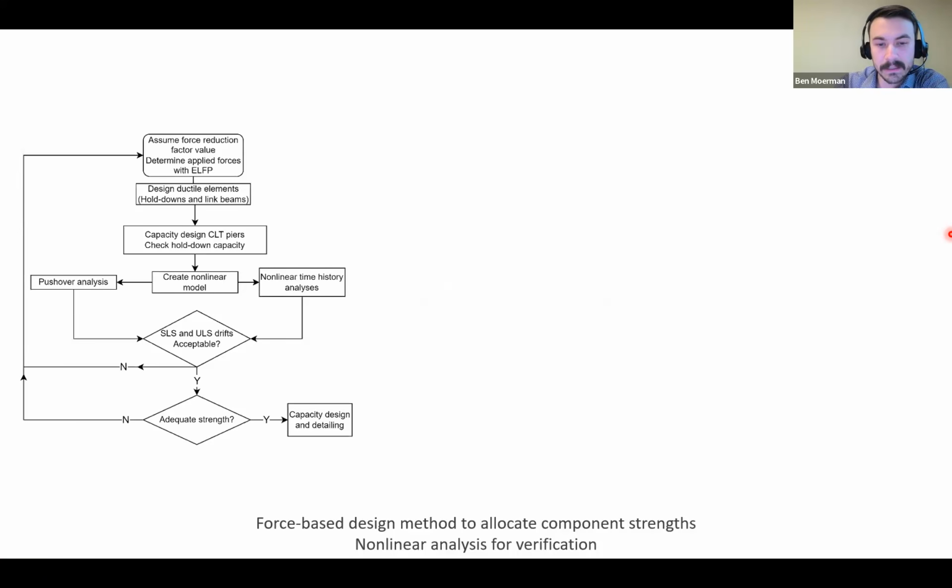What we proposed is a force-based design method, so you can allocate the component strengths with a final nonlinear analysis. So this is an iterative force-based design, and it's not the most simple design method out there, but I do feel that it's necessary for this system. And that's the great thing about doing academic research: we don't have to come up with the simplest method. We have to come up with the right method where the system can be designed well. And in my opinion, this was the best way to do that.